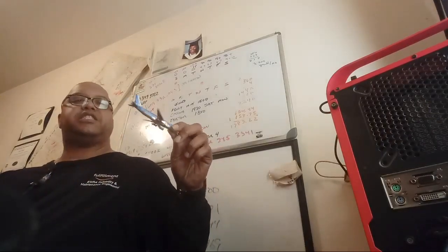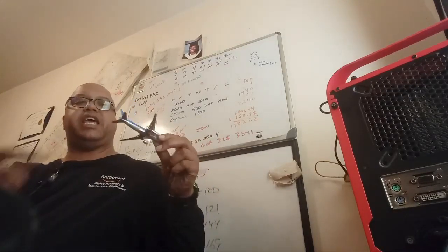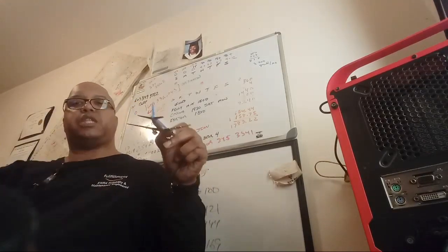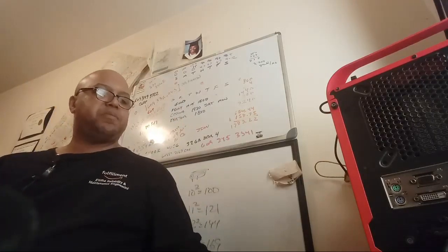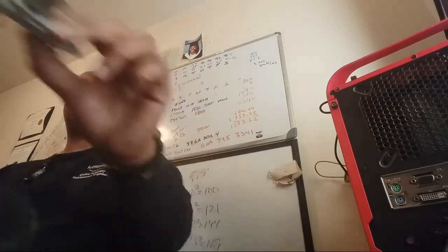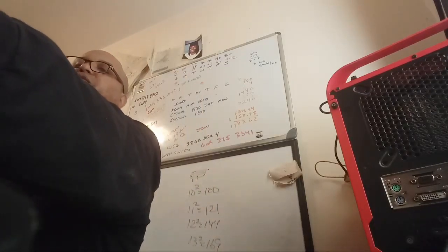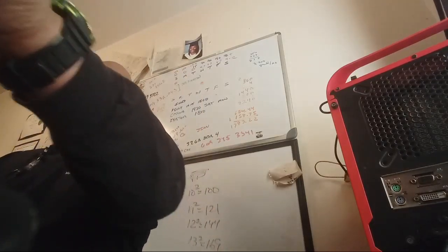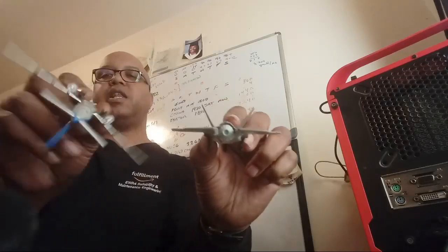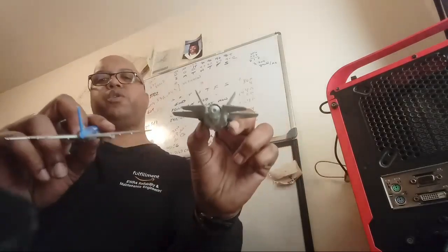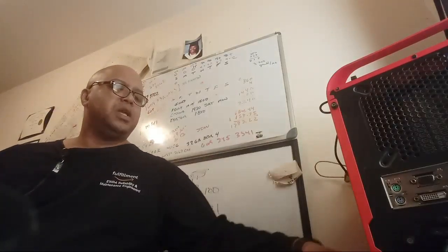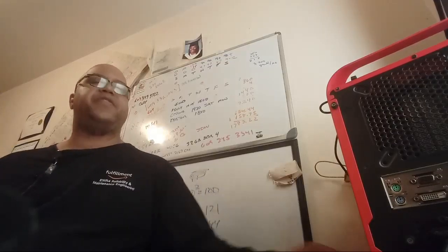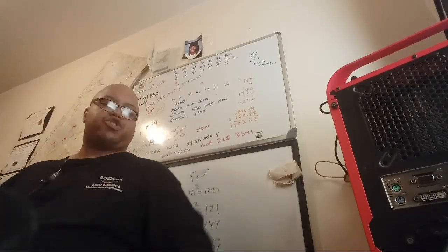The empennage, it's a French word, but it means tail section, and it consists of a vertical and a horizontal stabilizer. You can see kind of like that inverted T formation. Sometimes you'll have a slant in your vertical stabilizer. The horizontal stabilizer is still horizontal in this case, and I'm putting it up to the camera. All right, so you could have like a T, or you could have like a little slant. It depends on the design of the aircraft. Okay, very good, empennage.